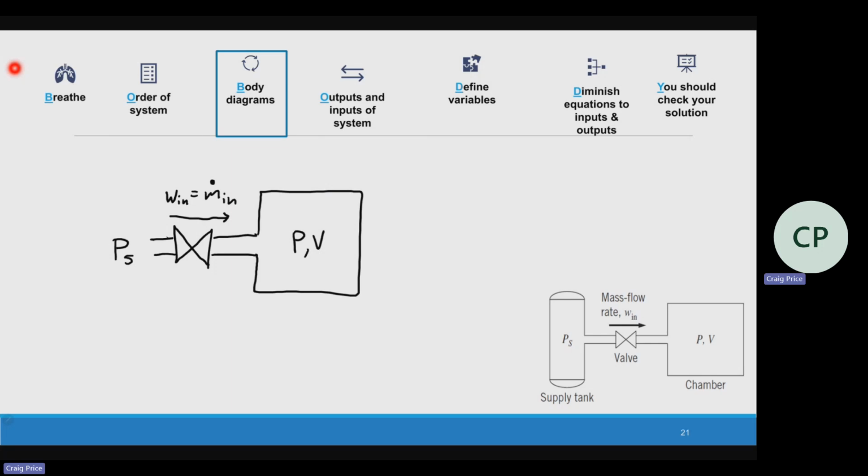So this tank has capacitance. We've got a supply pressure. Just like with hydraulics, I have a change in pressure. So it's going to go from high pressure to low pressure across a resistor, across a valve, gives me a flow rate. Now, in this case of a gas, I'm not using Q's, I'm using m dot, because density can change as the pressure changes. Here I could also look at temperature. So the temperature of the chamber also can affect what's going on equation-wise. Everyone good?